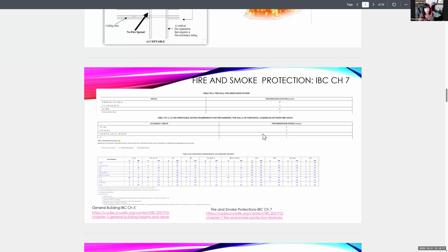I know the construction type, and you might say, based on what I know, they would have had to make this a fire barrier wall. You can actually do deductive reasoning and figure it out. Here's also Table 508.4, separations between occupancies.